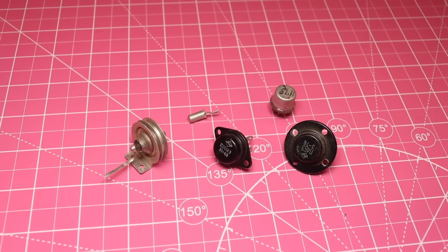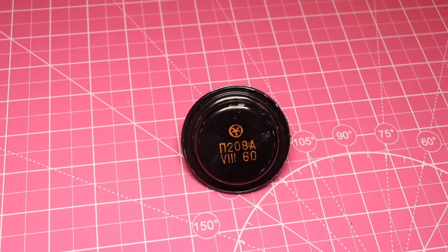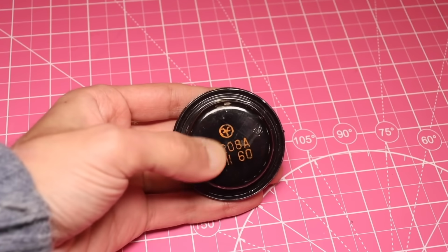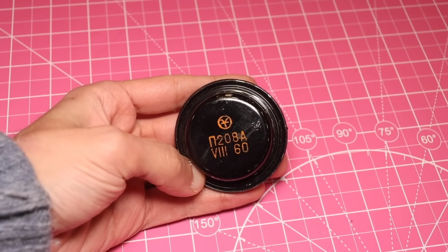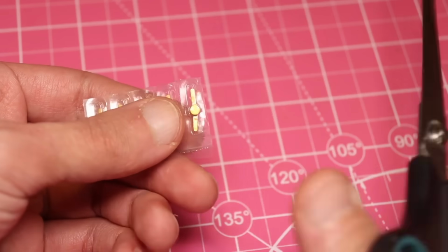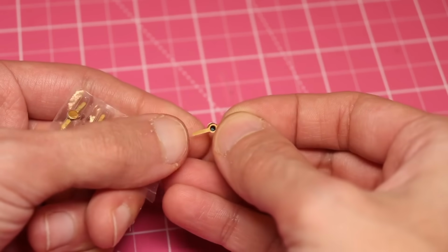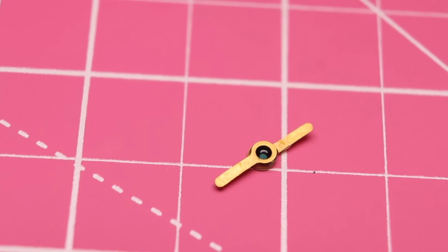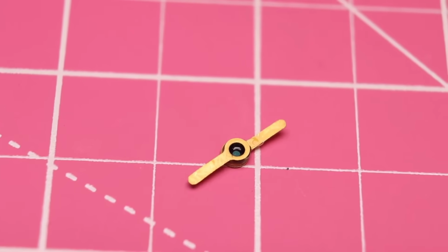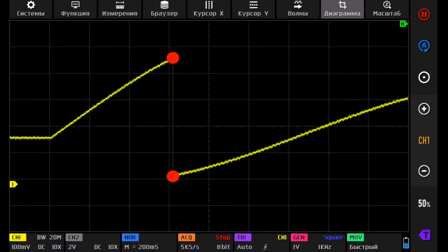So the transistors of that era, the late 1950s, could operate at frequencies of tens or hundreds of kilohertz. In rare cases, the frequency exceeded 10 megahertz. The switching time of these dinosaurs was quite long. But the tunnel diode is capable of switching quickly, extremely quickly, in less than a nanosecond. For it, cutoff frequencies in the tens and even hundreds of gigahertz were achievable, which made it possible to use them in cutting-edge long-distance communication equipment and in ultra-fast logic circuits.